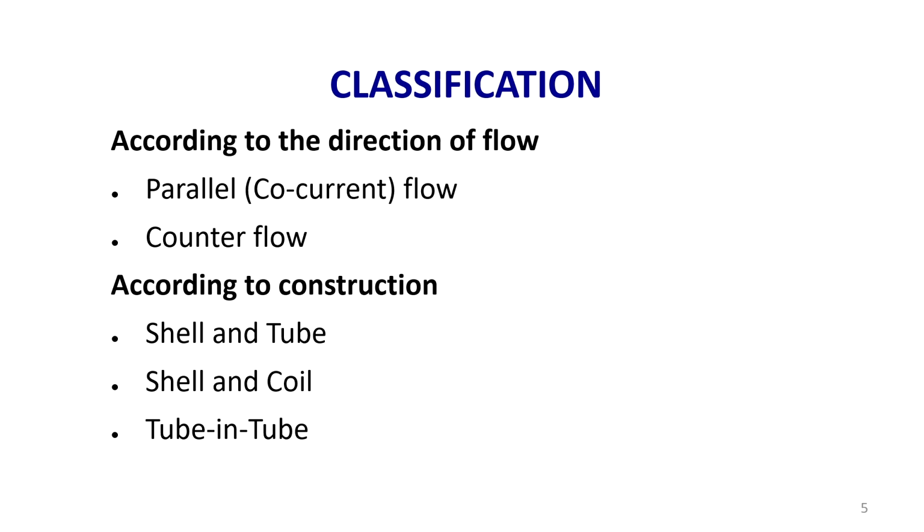There is a tube inside in which fluid is passed, and there is another tube surrounding that one. So, there will be a gap, that is the annulus portion between the first tube and the second tube. In that, the second fluid will pass. So, there is heat transfer. So, that is tube in tube.